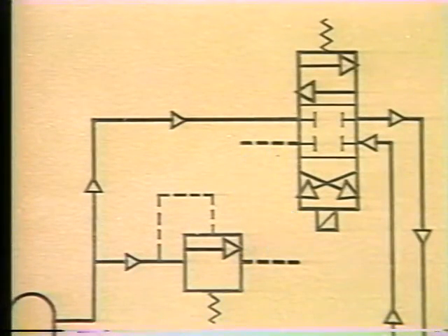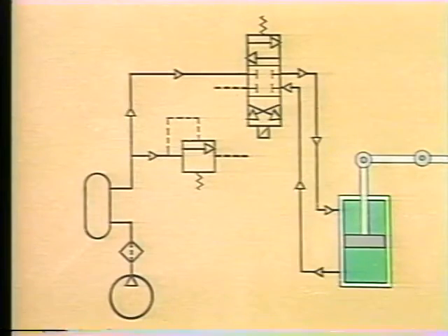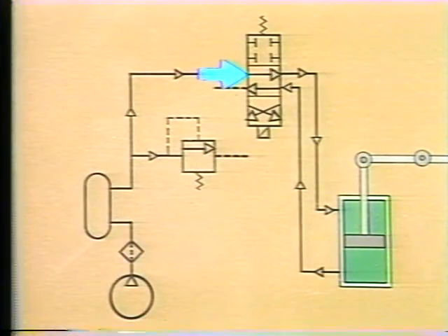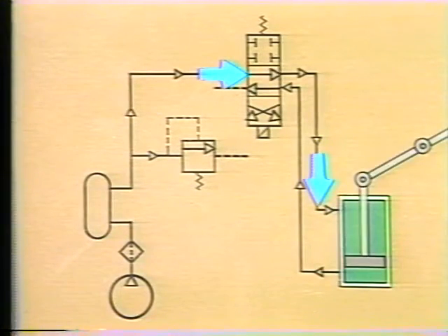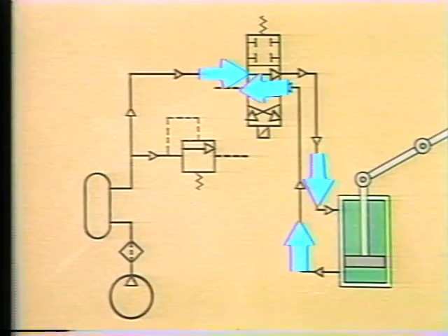In the hydraulic system, the fluid drained back to the reservoir. The basic operation of this pneumatic system, though, is the same. Compressed air is applied through the directional control valve to the upper side of the piston, forcing the piston down. Air under the piston is vented to atmosphere through the directional control valve.